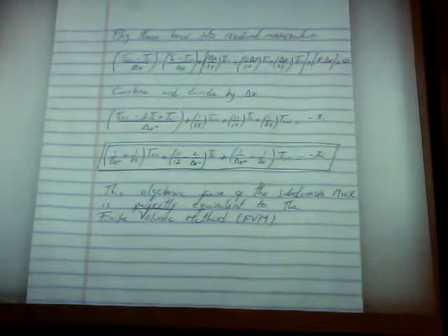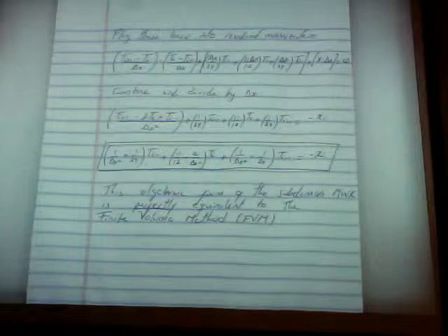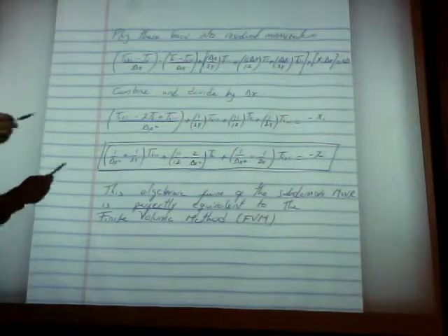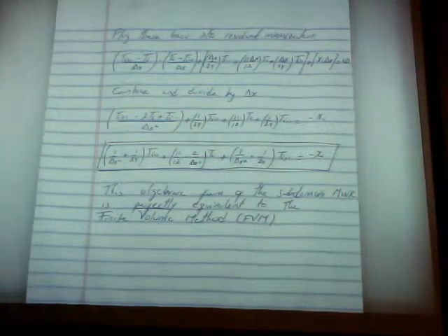It is a very common technique. It is as common as a finite element method. You use finite element every time you use CATIA and do structural analysis, or every time you use ANSYS and do some structural analysis. The technique of choice for structural analysis, solid mechanics, is FEM. But every time you do CFD, under the hood of the code that you're using is a finite volume solver. Okay? Whether you use Fluent or CFX or STAR-CCM+, whichever one of those solvers you elect to use for computational fluid dynamics, the technique of choice is finite volume methods.